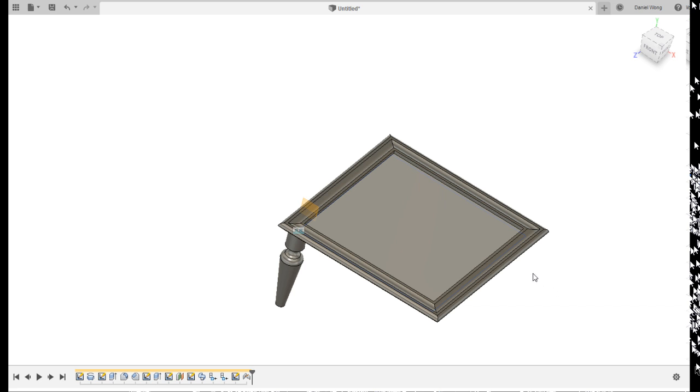And look at that. We have our first leg of 4. Great. So, now that we have that leg, we can do the same for the other 4 legs. Other 4 legs. There's actually a mystery leg in the middle. And so you can think of multiple ways to do this, right? One way you might have, yes? You can do rectangular pattern. You can go into create and we can go rectangular pattern. Good suggestion. Which is one way. But my problem is whether it actually mimics the joints. Now, I believe it does, but I'm not 100% certain, which is why I prefer to do it by just placing new legs.